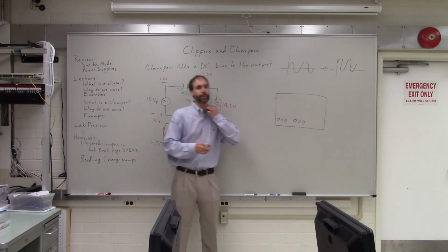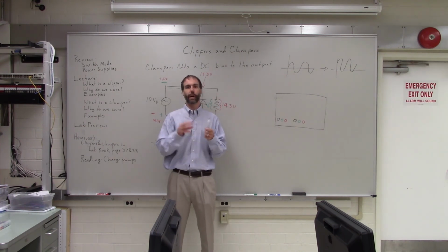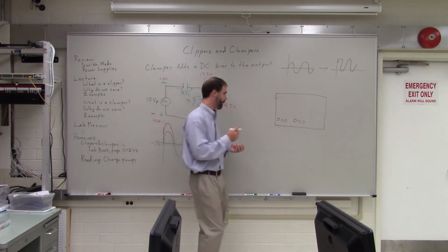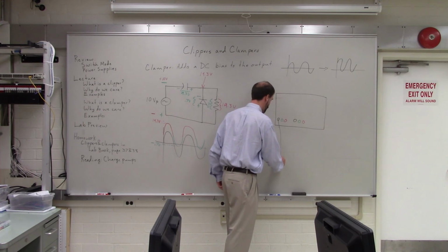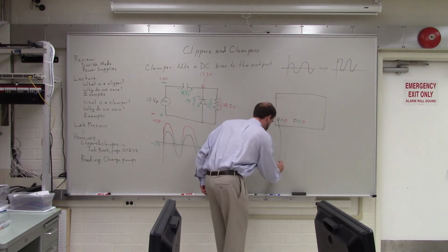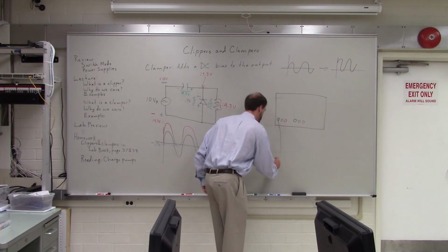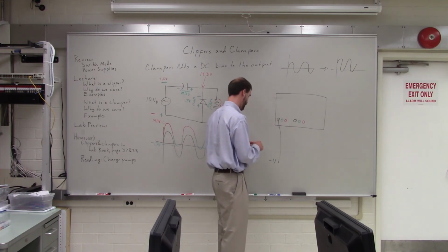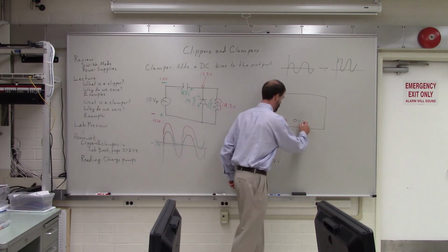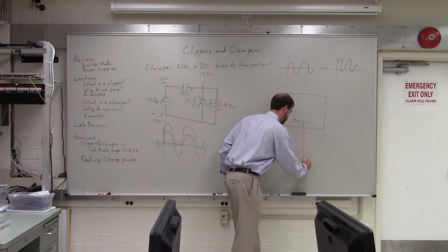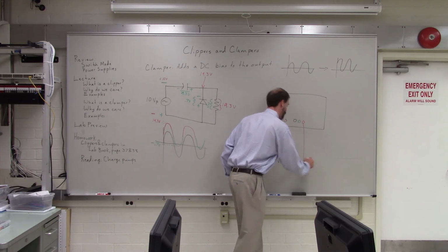In order to get a negative supply, you need to take one of those wires that has 3 cords in it. You'll hook the black cord over there. So this is the negative output, the negative voltage output. The red cord is over there. This is the positive voltage output.